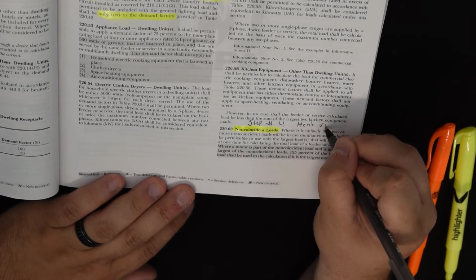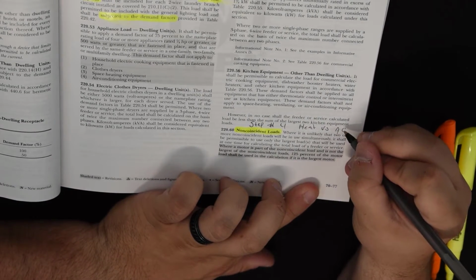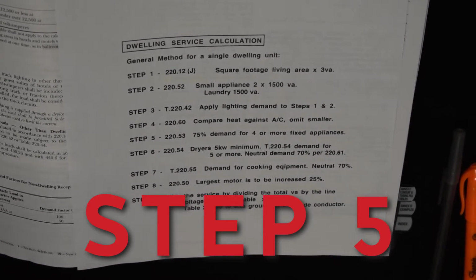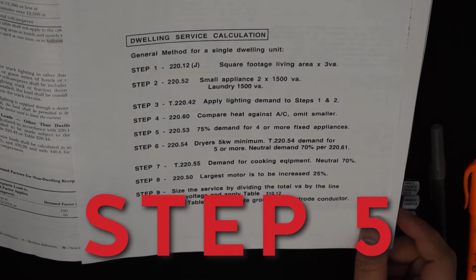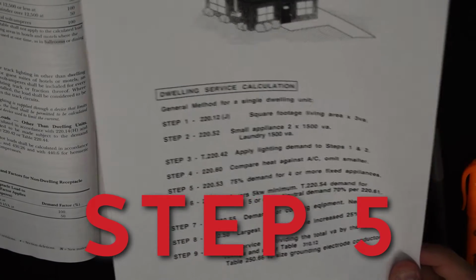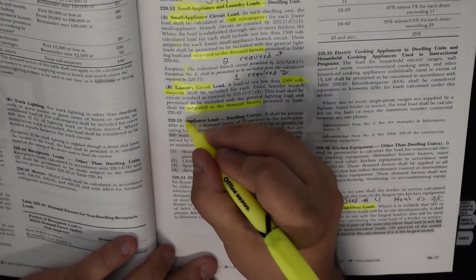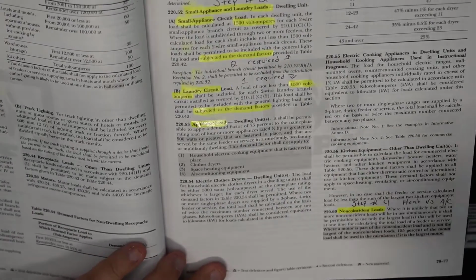You shouldn't have the heat going at the same time you've got the air conditioning going, and that's what this code is referencing. Step number 5, don't get confused on step number 5. It takes us to 220.53. It says 75% demand factor for 4 or more fixed appliances. If we've got 3, 2, or 1, that does not apply. It's 100%. So let's look at 220.53. Highlight appliance load. Once you get that, go ahead and write step number 5.